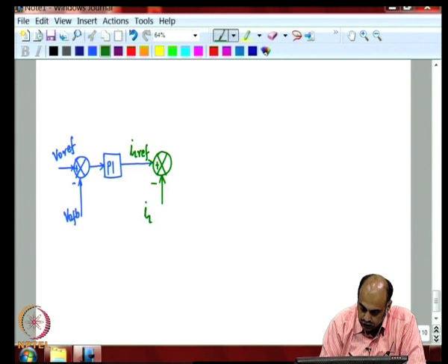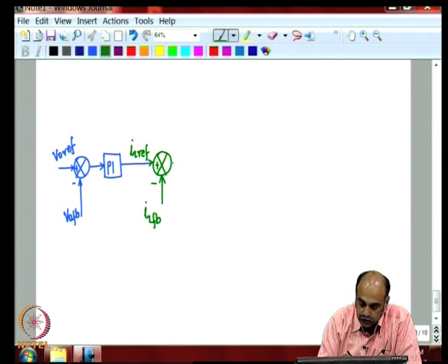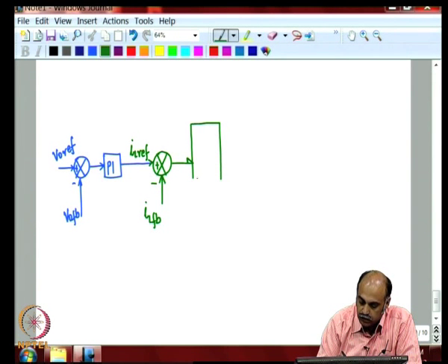We shall compare with IL feedback, and the output of this passes through appropriate Schmitt triggers and is given to a set reset flip flop. The output Q.